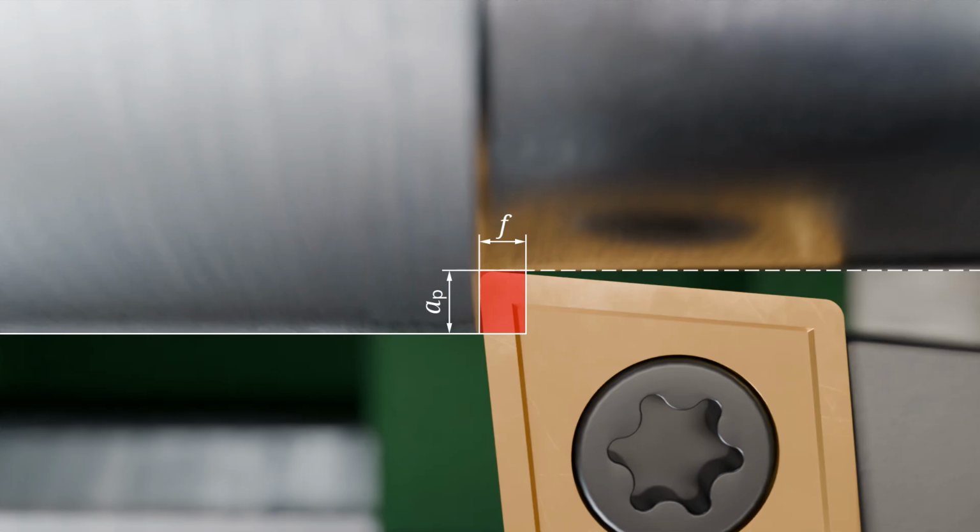Cutting speed has an even greater effect on tool life. At high cutting speeds, heat generation increases significantly. This causes the cutting edge to overheat, and the strength of the cutting material decreases, meaning the cutting edge essentially softens. This results in increased wear of the cutting edge. However, cutting speeds that are too low should also be avoided, as this can cause material to stick to the rake face. This phenomenon is called built-up edge formation. Such built-up edges lead to poorer surface quality and ultimately to increased wear. Therefore, the manufacturer's recommended cutting speeds should always be observed.